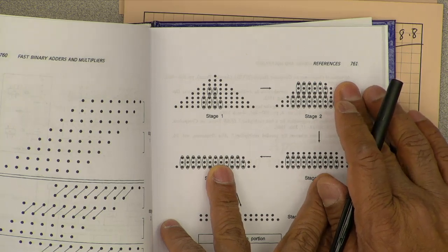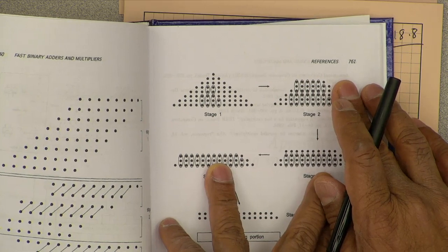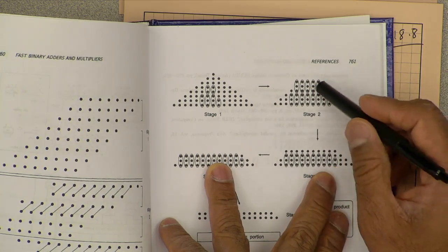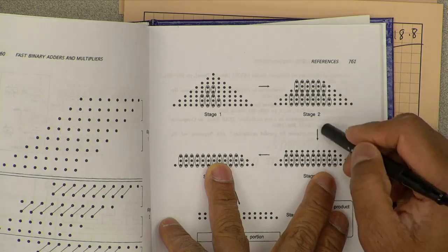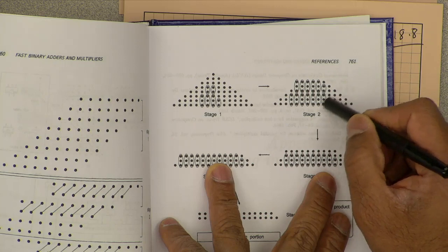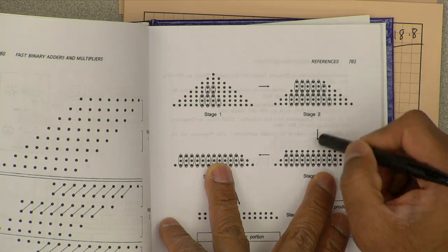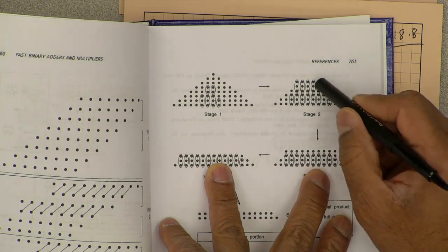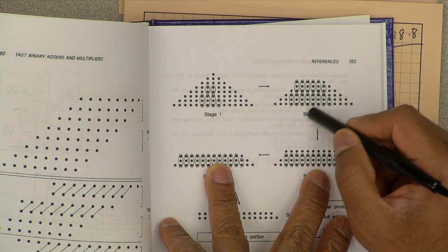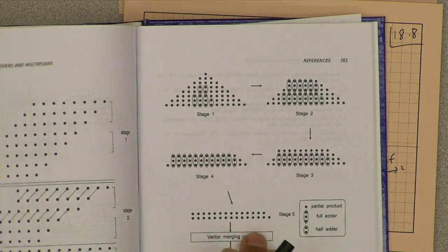Fifth column new depth is 4, because that 2 in the circle becomes a half adder, giving a sum and a carry. So now the new depth is 4. Now what is the new depth of the next column to the left? So 1 becomes 1 dot and another dot carry from the right-hand side. So that becomes again 4, and this becomes 2 dots and 2 to the right circle come 2 more carries, that becomes 4, and so on.